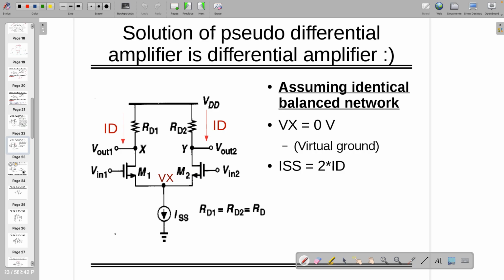So if we are going to have such a circuit where both the balanced networks are identical to each other and they are connected with a wire, if both sides I am connecting the same voltage, then the current flowing through this one is double, right? If one side it's V in and another side is minus V in, means 180 degree phase shifted, at that time this is acting as a zero, or it's a virtual ground. There is no matter what you are connecting here, forget about that one.